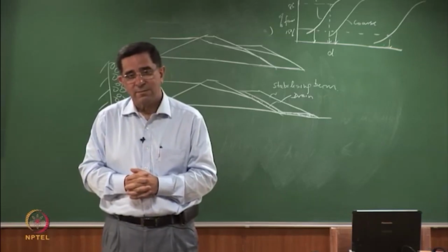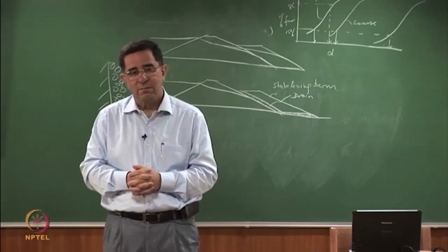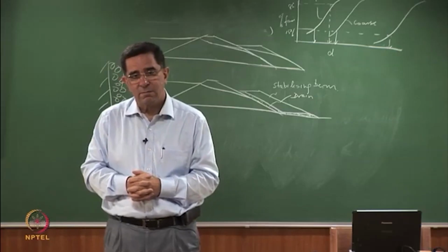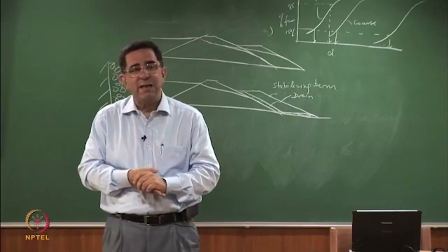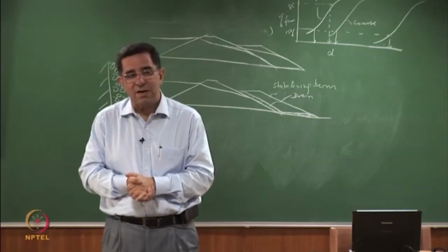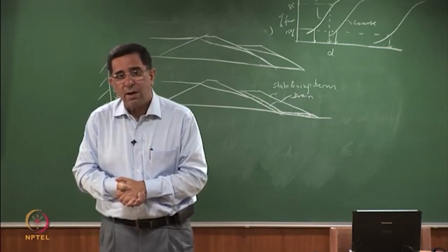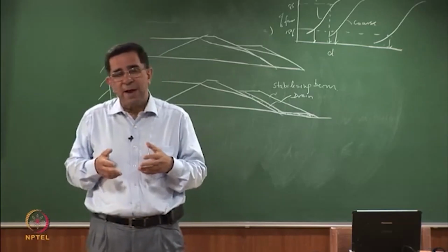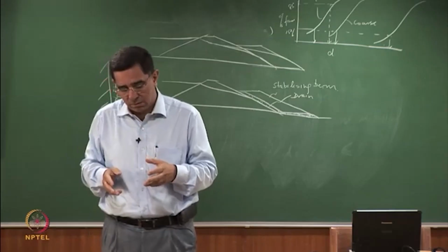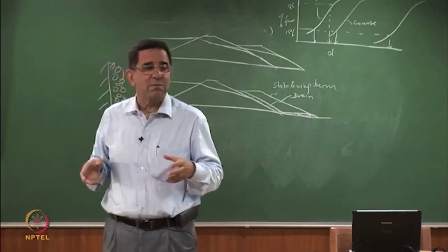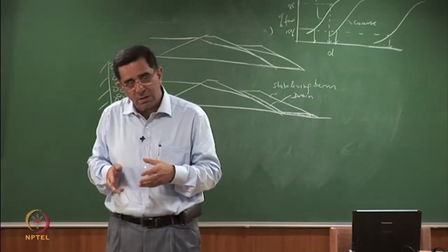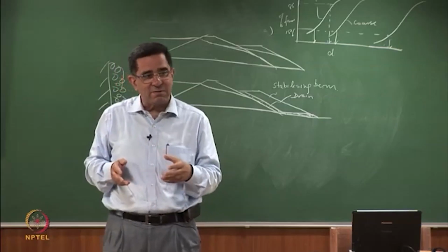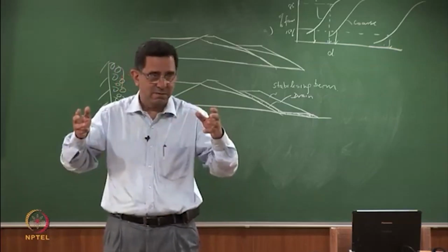Other than this stability criteria, is there any maximum permissible settlement for upstream wells? Question asked is there any maximum permissible settlement for upstream method? So the embankments that we are constructing by the upstream method are all flexible embankments, and they work on the principle that if any embankment settles, the crest will be raised.